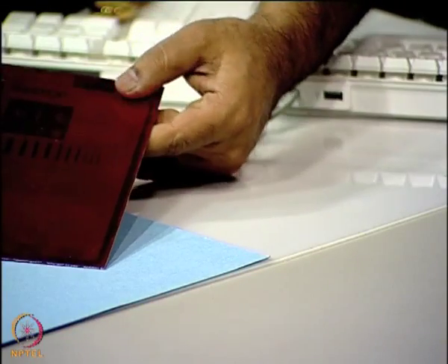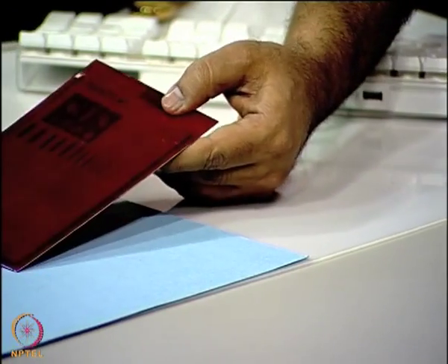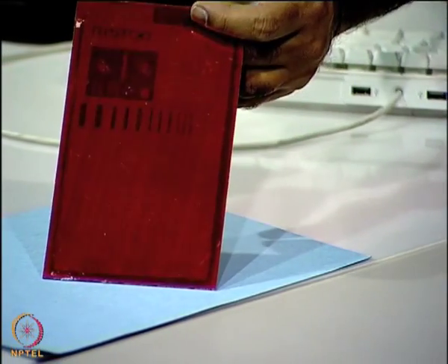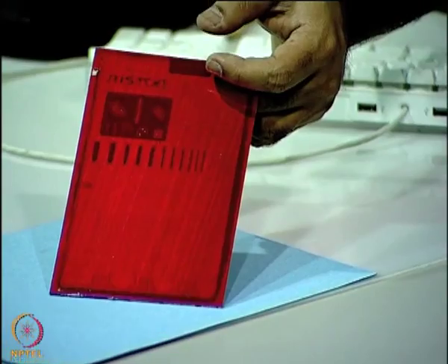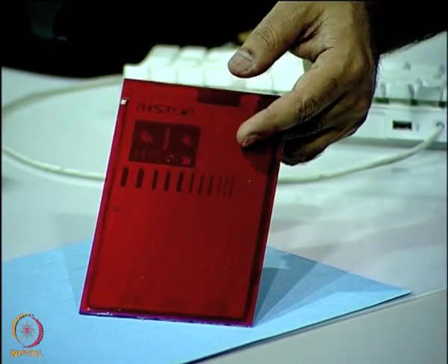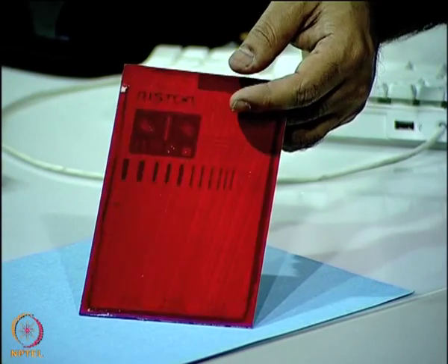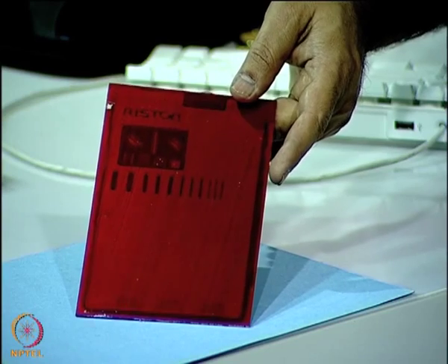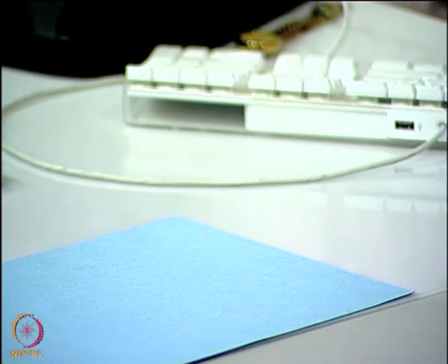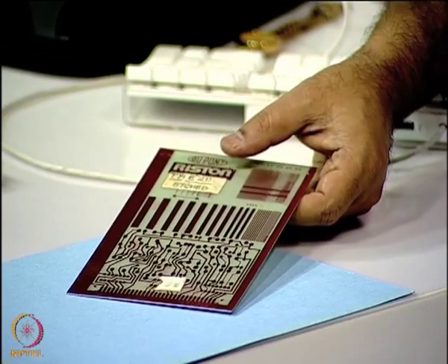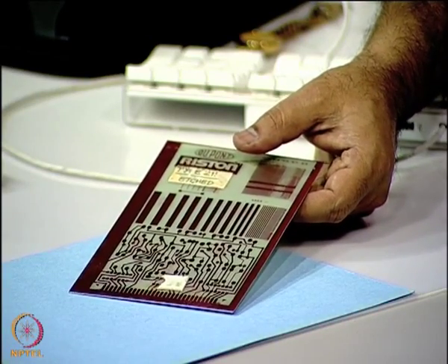I will also show you some of the samples that have come out through those processes. You can see here this is a photoresist coated copper clad laminate. The red material, dry film, that you see here is a photoresist material. Now, this is imaged, as you know, and then it is developed. So, you can see here after the photoresist